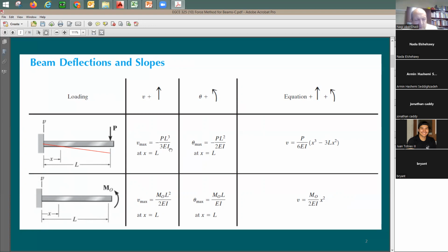I guess this is also the same equation I used when finding the stiffness factor. If you remember the horizontal, lateral forces, we said K, the stiffness factor, is equal to 3EI over H cubed. So with that, I don't really need to do the conjugate beam or the virtual work analysis. I can just look it up from this table and use it.